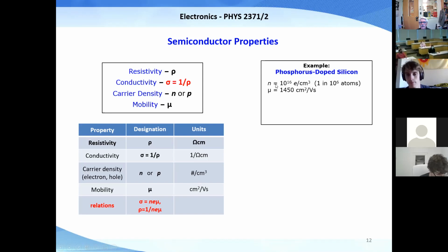If we know what the carrier concentration and the mobility are, we can calculate the resistivity, and we get something like that. Just a number, but these are typical numbers. And in the advanced lab class, we'll actually measure carrier concentration and mobility of a piece of silicon. So that's maybe in your middler year.